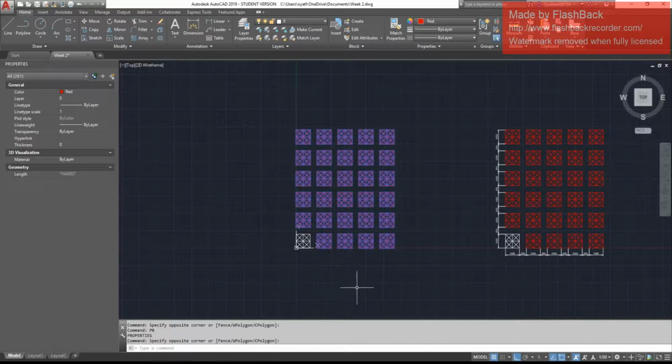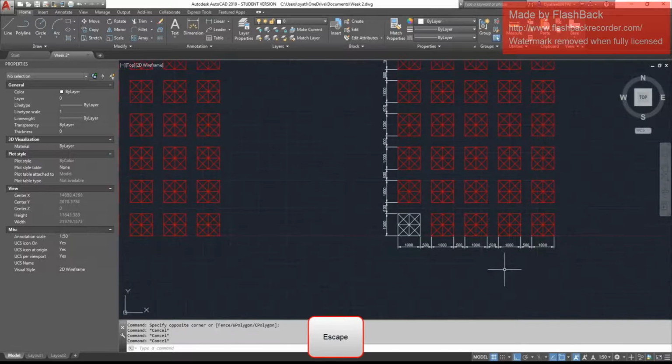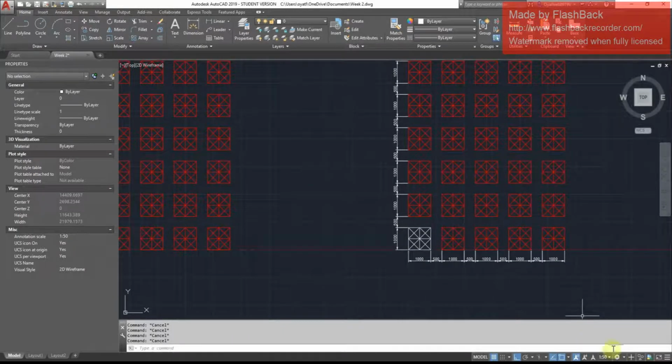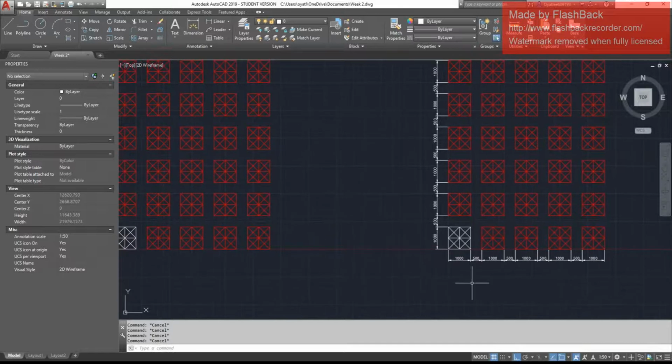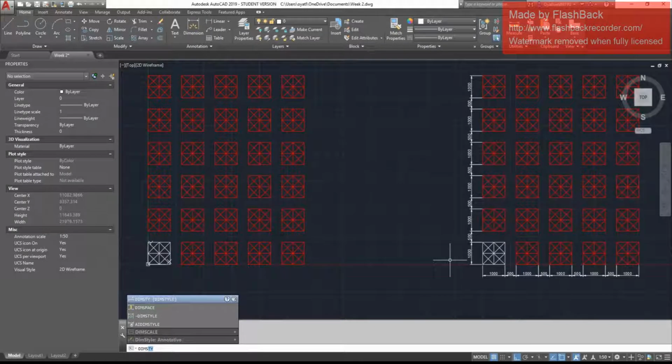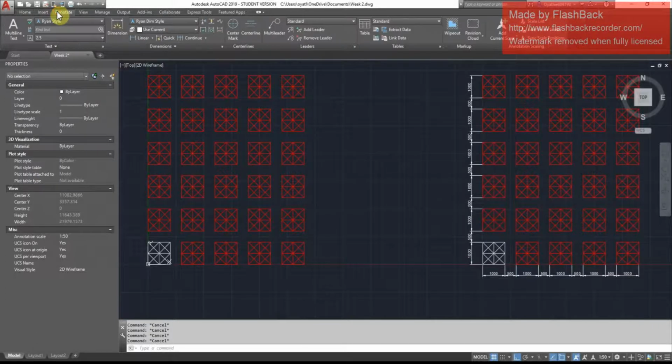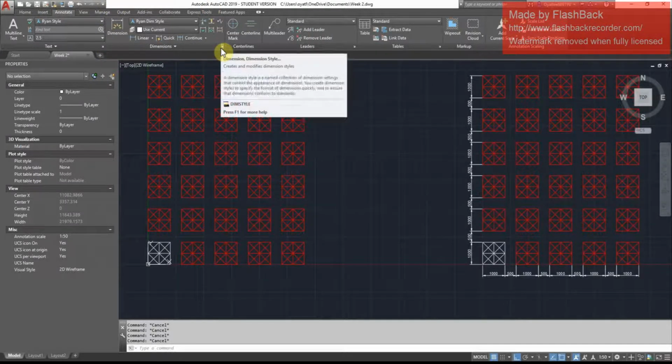Okay, to do these dimensions the way you want them, what I changed was the drawing scale to 1 to 50. It's not the fixed answer, but for the size of the object that I've got, it just fits with a 1 to 50 scale, right? And to create your dimension style, DIMSTYLE, which is dimension style, that's the shortcut. Or you can get back to your Annotate tab and Dimensions ribbon panel. You have that small 45-degree angled arrow shown, which is the dimension style settings.